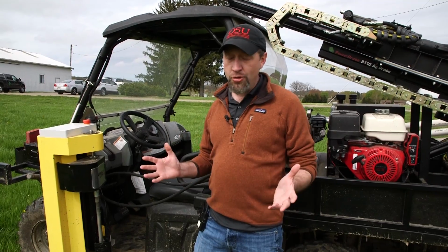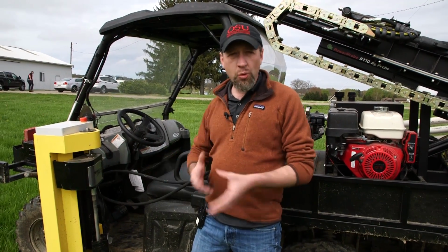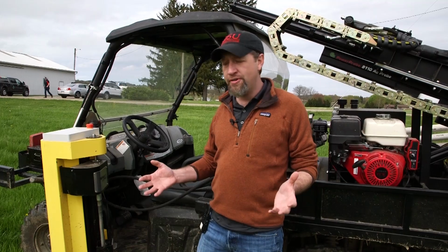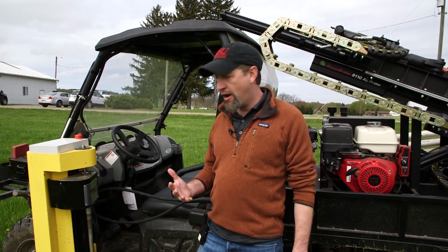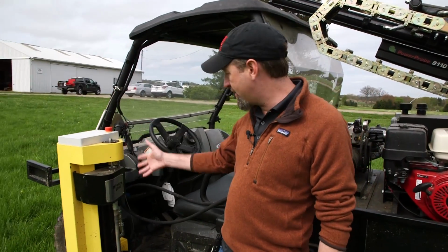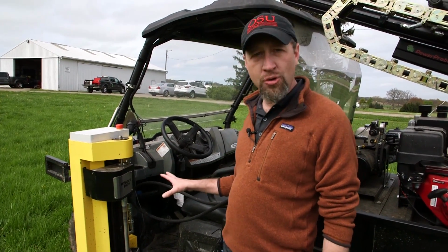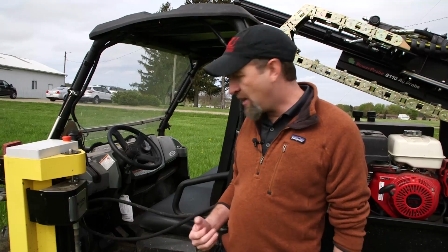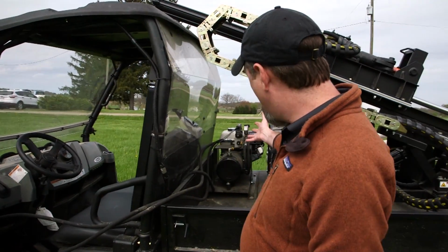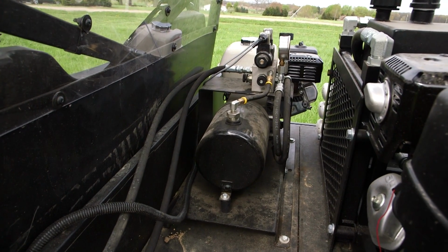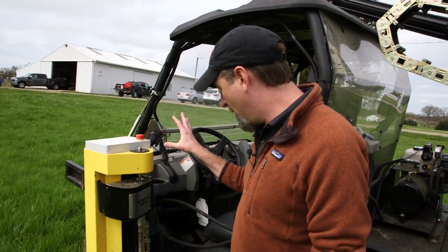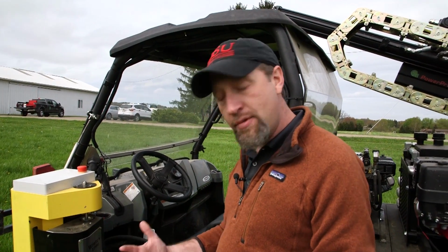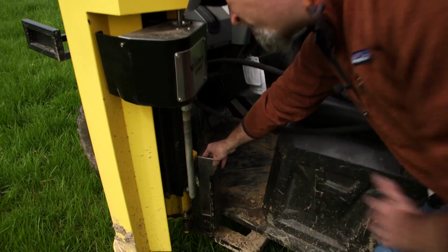While many folks still soil sample with a hand probe, one of the ways that the industry is moving forward and trying to make this fairly labor-intensive process of collecting soil samples more efficient is through the introduction of soil sampling technology. So what we've got here is a hydraulic soil sampler. This particular model is made by Wintex, and the idea is that we can use hydraulic power starting from a Honda motor to power the hydraulics to push a probe, very similar to what we were pushing by hand, down into the ground, and it will collect that core and deposit that core into this cup.